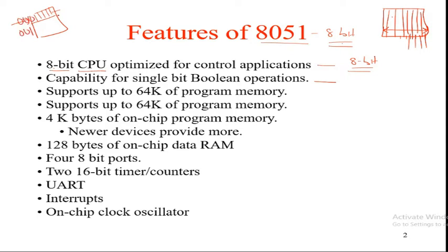So in the memory device, each and every memory location, suppose the 0th memory location or the first memory location, can load only 8-bit data. Whatever memory chip you take, whether 64K, 100 kilobytes or 1 megabyte, every memory location can load only one 8-bit data, that is 1 byte. In the microprocessor, this complete 8-bit data is taken at a time.